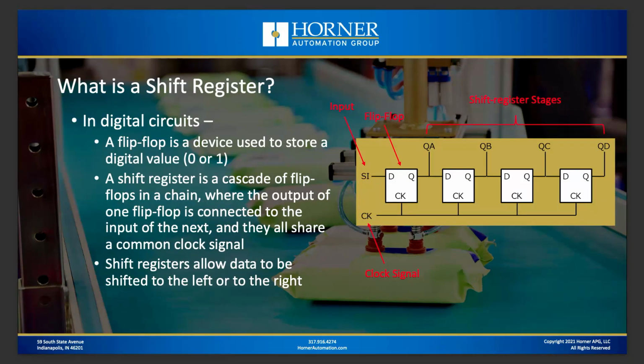For those of you with an electronics background or an engineering background on the hardware side, you may think of a shift register from a digital circuits perspective. You understand that a flip-flop is a device that's used to store a digital value, a binary value of 0 or 1. And if you cascade a series of flip-flops in a chain, connecting the output of one to the input of the next one in the chain, you have now basically created a shift register, provided that they're all controlled by the same clock signal.